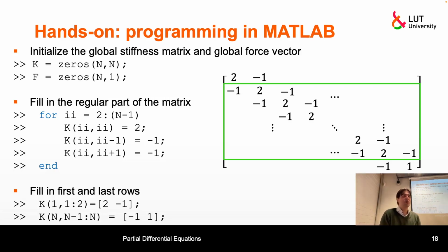Because that is actually what we will be doing in finite element analysis. We will form a matrix for a single finite element, a stiffness matrix. The name is general, though it might be a heat conduction problem. And then we will position them accordingly, according to the number of the certain element, and then we will sum them up. And that would produce this global stiffness matrix.